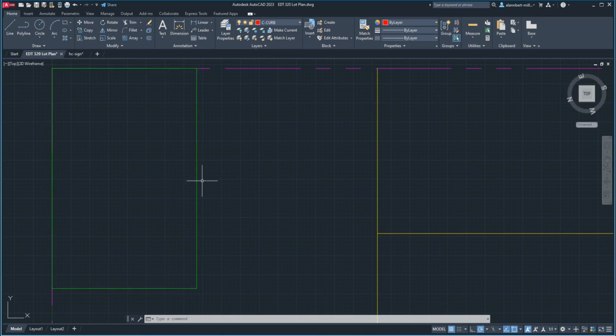Okay, so just do a line and then type mid, enter, and then point here, and then just do a short line there, press enter. That's going to be in the middle of the gate. This is 12 feet. We take a foot away from here, okay, and a foot away from here. That's 2 feet. That means that the gate will be 10, and that means that this gate is going to be a 5 by 5, okay?